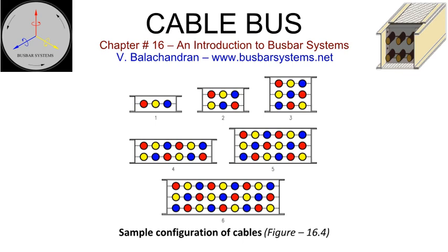They shall have a minimum degree of protection of IP55. Tin or silver-plated copper adapter plates may be installed at the terminals for interfacing with the cables from the cable bus. Non-magnetic gland plates with cable glands will seal the terminating cables. Often, the outdoor end can be directly terminated onto the outdoor bushings of the transformer. Care should be taken to ensure that the outdoor cable terminating kit meets the requirements of the service condition.